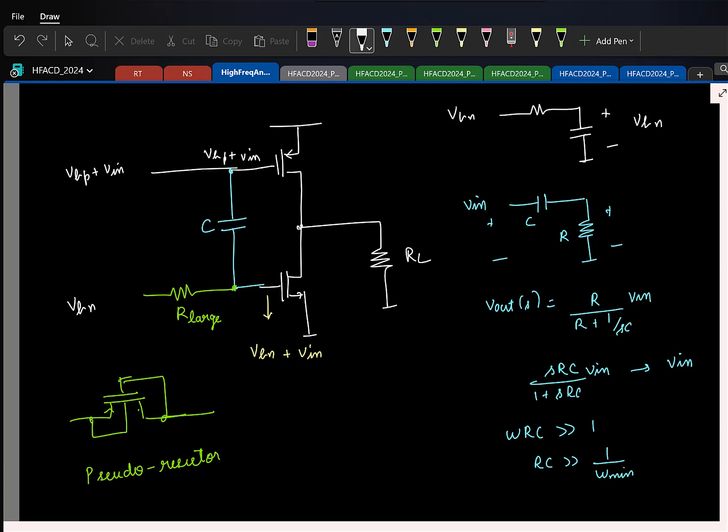And as mentioned, typically it's required because one simple way to make an amplifier is this, an inverting amplifier, to get an accurate gain. But if you use a resistor here, the resistor is going to generate noise. So what else can I use to get an inverting amplifier?